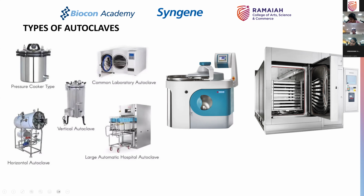And then the junctions were made rounded, with a slight curve, so that you didn't have 90-degree angles where particulate contamination, and therefore microbial contamination, could lodge. It was self-cleaning, in the sense that if something got stuck here, it would anyway slide down because there was a rounded edge. So it's like a rounded edge on a rectangle at the top, which is what you see here also. You see that there's a rounded edge here. If you had a rounded edge inside the chamber, you would not have the fear of any contamination getting stuck there. So rectangular chambers were used.